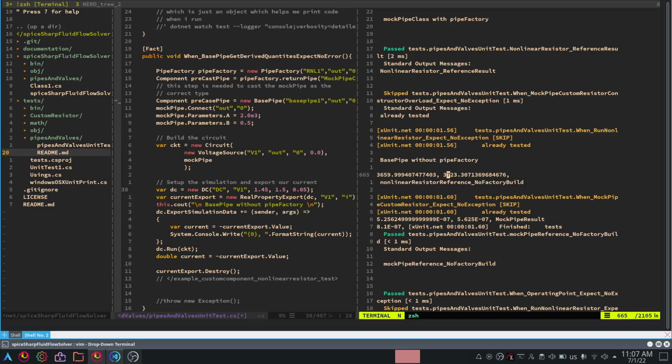Do note that the kinematic pressure is 1.45 meters squared per second squared. This pipe is carrying water, so that equates to about 1.45 kilopascals. That's a lot of pressure drop for one pipe. So you can imagine the flow through this pipe must be a lot for this much pressure difference to accumulate. However, I have not checked whether this value is possible just yet, and that will actually be the next part.